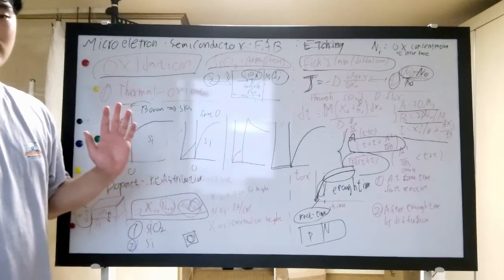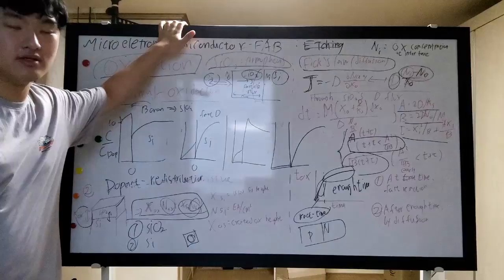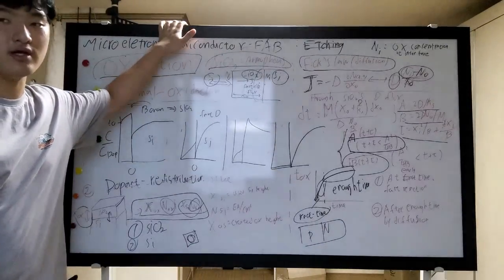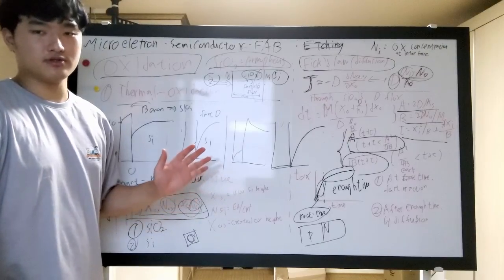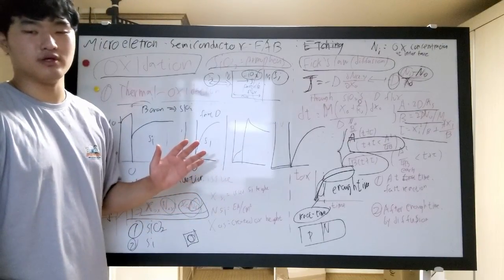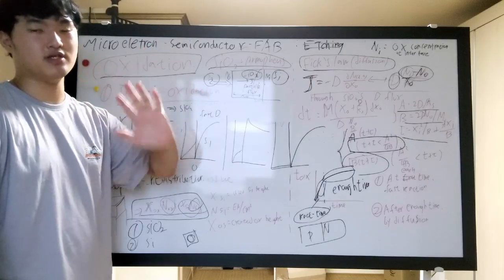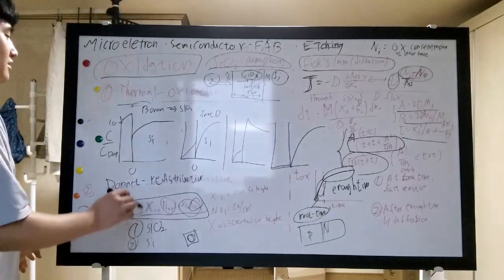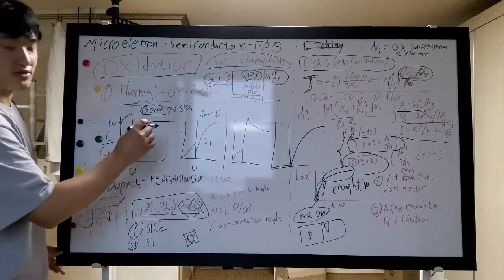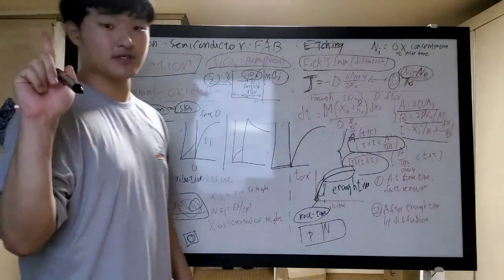And for the silicon dioxide that has just been made, we will have some lack of borons, because during the oxidation, the boron will decide where it should go: to the silicon inside, staying here, or going to the dioxide side. So first, if the dopant has moved to the dioxide side, here's the case.